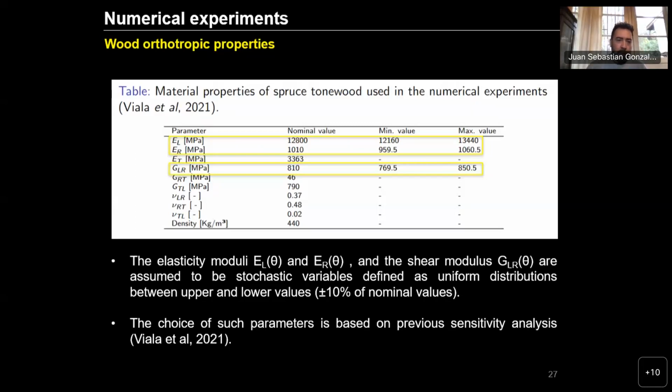We use Salome for the geometry. It's a French software, open. Everything here was made with open source software. So we use Salome Meca for the geometry and for the mesh, and for the finite element analysis, we use the Code_Aster solver.